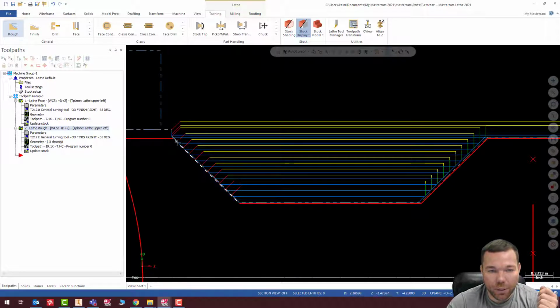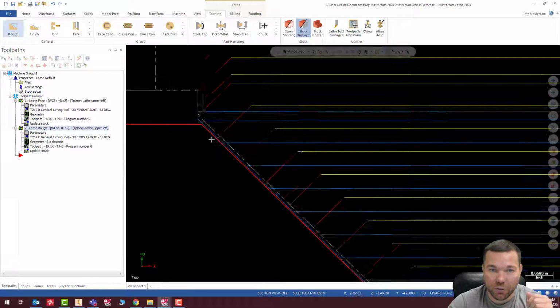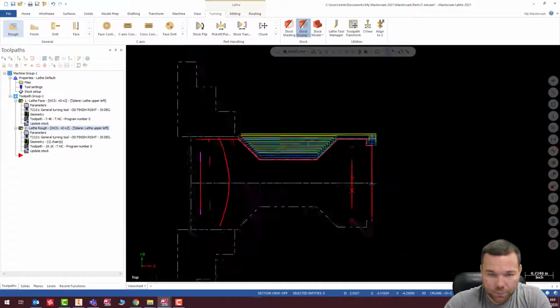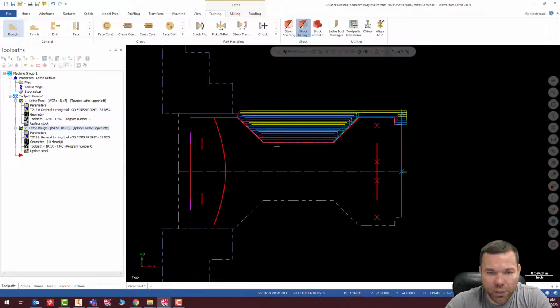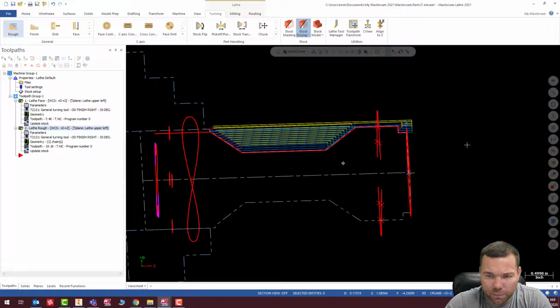Here, it's not going to be noticeable because all I need to do is turn straight back past that angle that I created. That's also why I extended it a little bit so it goes past. So that corner will just be perfect. You won't see any kind of mismatch in concentricity. So I always try to use a change in direction if I'm going to match turn something. All right, so that looks good.